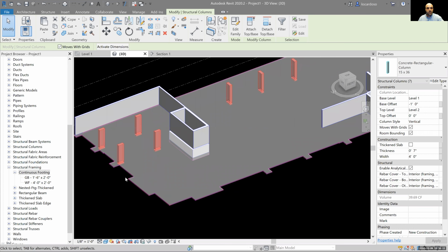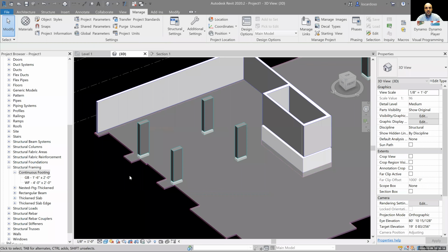You can see what Revit thinks is more important. Revit doesn't really care about materials, right? It doesn't care that this is a slab on grade concrete floor or that those are concrete walls. It just sees vertical and horizontal. So we know, because you're in construction or you want to learn more about construction, you Google this stuff, that a slab on grade floor pours around a column. So let's do that change.